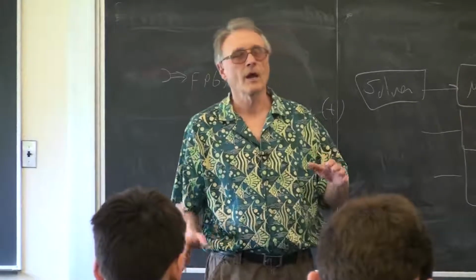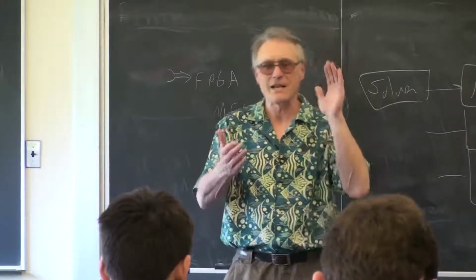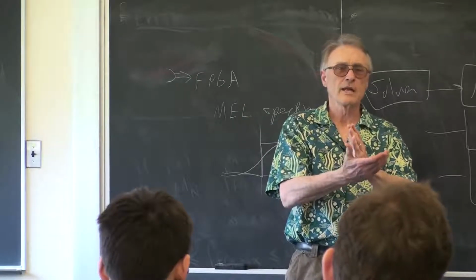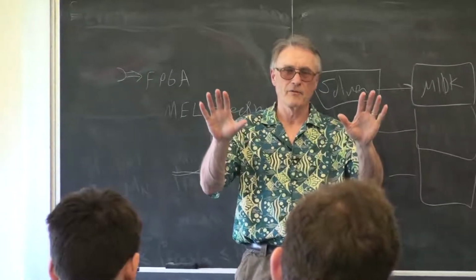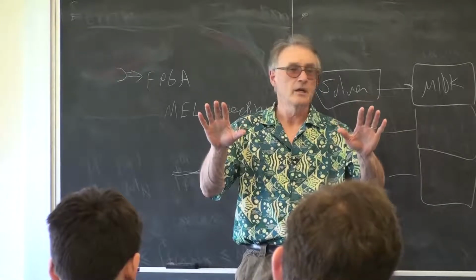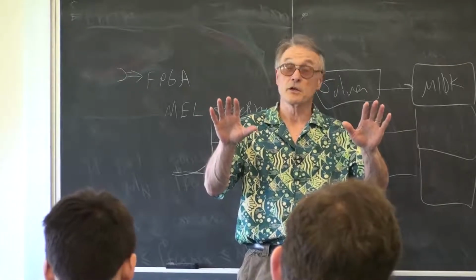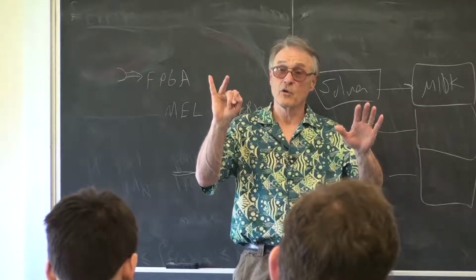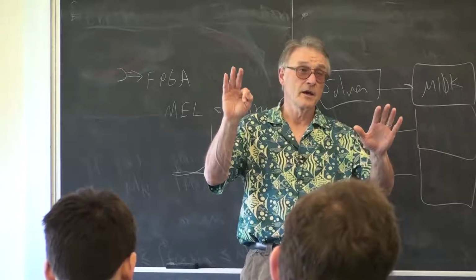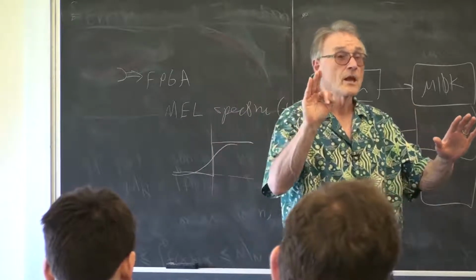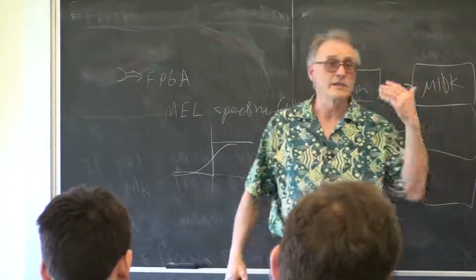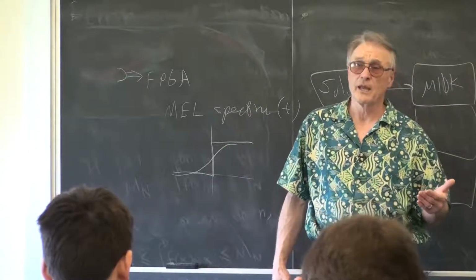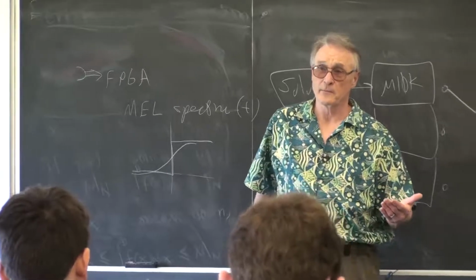Informally, I've tried just one bus master writing as fast as I could write to the VGA memory, which is now only in SD-RAM. So I modified the code so that SD-RAM is shared 3 ways. It's shared between the HPS, the VGA controller, and a bus master. So it's being hit continuously to update the VGA display. The question is, how often can you write to it and not destroy the VGA display?